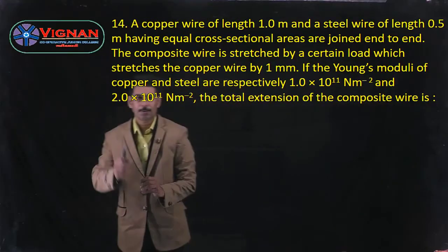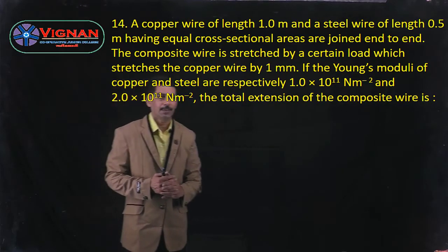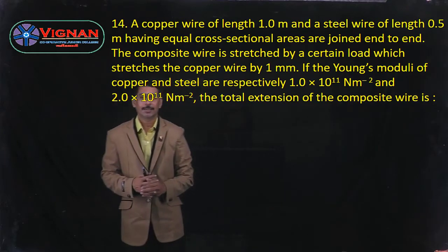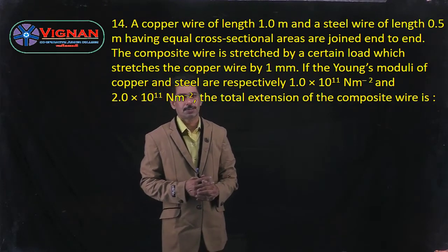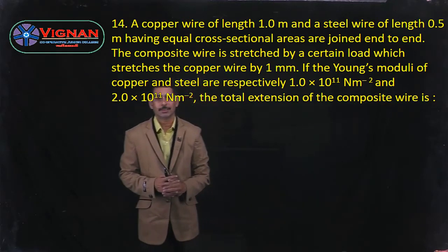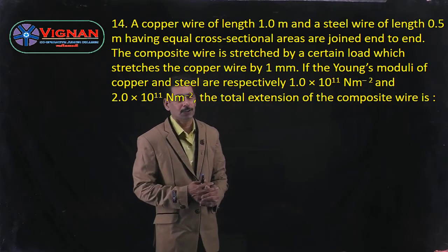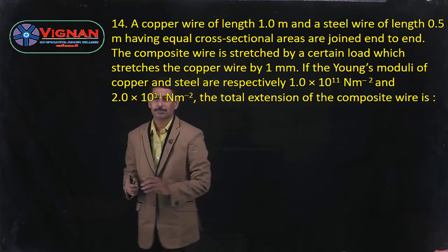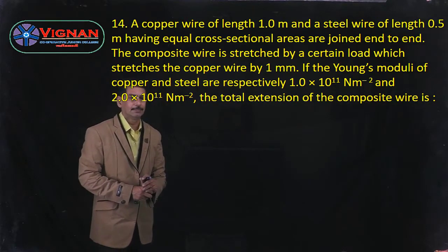So the next problem: a copper wire of length 1 meter and a steel wire of length 0.5 meter having equal cross-sectional area are joined end to end. The composite wire is stretched by a certain load which stretches the copper wire by 1 millimeter. If the Young's modulus of the copper and steel are respectively 1 into 10 power 11 Newton per meter square and 2 into 10 power 11 Newton per meter square, the total elongation of the composite wire is...